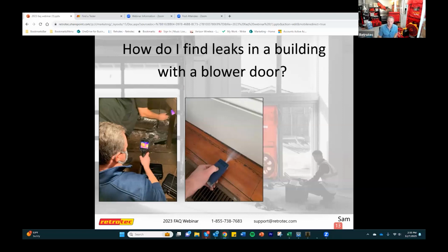And you can do it with a larger smoke machine too. We actually carry one that you can fill an attic with, or a room with. So we have testers that will fill an encapsulated spray foamed attic with smoke, pressurize it with the attic door open so that the attic gets to pressure as well, and then walk around outside and see where it's coming out. And it's almost always at the soffit where they just didn't seal well, where they couldn't get to it. So if you are going to go that route, it's going to look like the house is on fire from the outside. So just let the fire department know you're doing that, or the neighbors will call. And sometimes that can end up with a fine. That's happened before. So just keep that in mind if you go the big smoke route.